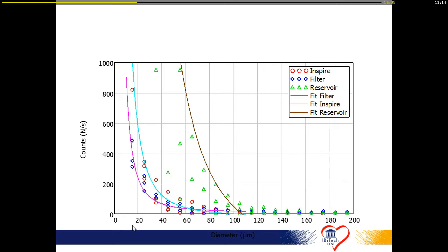Now, let's enlarge this a little bit. What you can see is that the protection, whether you have a filter or not, at the level of 40 micron is extremely small. And there is only a very minor difference in favor of an additional filter if you go up to, let's say, about 20 micron. So we can really question, is this worth the benefit?